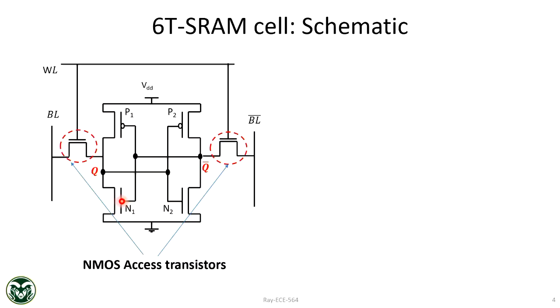we talked about leakage, right? These days in a lower technology node, transistors are always leaky. So even though this N1 is off, it will still try to discharge Q through leakage. If there was no P1, after some time Q would have discharged to zero through this leakage current. But because of this N1 and P1 combination, even if Q loses some charge, P1 immediately charges it back because P1 is turned on.